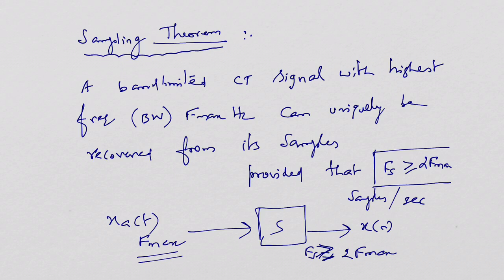We have told you everything about what is meant by aliasing, and we have told you about folding frequency. So how to restrict ourselves before sampling? We have to look into the maximum frequency, and the differences between two components if more than two components are present, and how to set the Nyquist rate.